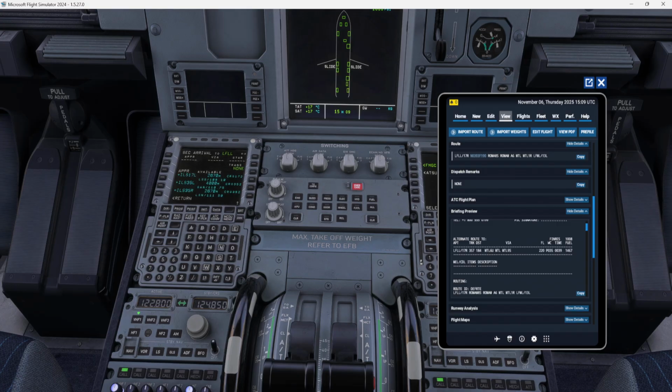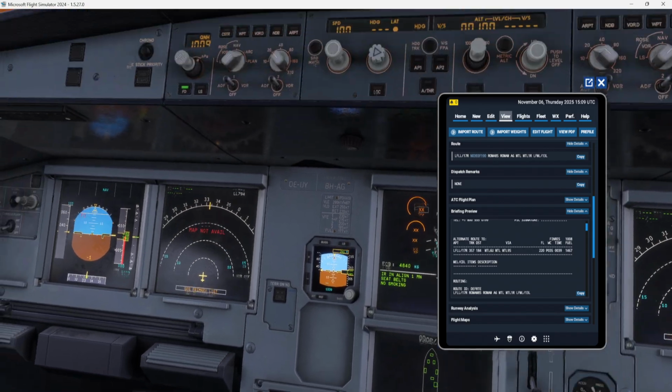We click on LFLL, new destination, arrival. Well, we have the LFLL, you know, but this is in case of engine out SID, not where we return back. So I will select 17. In this case, we return. We are taking off 17 left. I'm going to see where is the position of NEGPU.